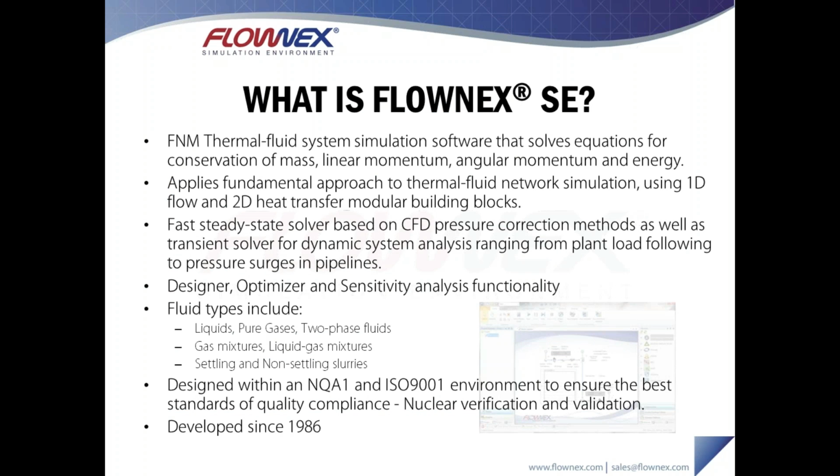All right, so Flownex itself is, as Luke mentioned, a one-dimensional flow and two-dimensional heat transfer network modeling software package. So basically what that means is it is almost a CFD-style software package where we look at modeling fluids in a traditional CFD environment. However, the building blocks are one-dimensional. So our simulations tend to be networks rather than three-dimensional geometry. These networks are then solved with a pressure correction method similar to CFD, and we use conservation equations of mass, momentum, and energy as our governing equations that we then solve with our differential equation solvers.